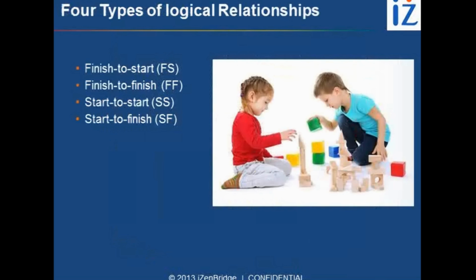Now, as I said, in the critical path method, each activity is related with another activity. There is a dependency. So we talk in the language of predecessor and successor. So activity A and activity B, which could be a successor, will have some level of relationship. So four types of relationships are used in the critical path method. Finish to start talks about, let me finish before you start. So you can't start till the time I am done with my work. This kind of relationship is called finish to start.